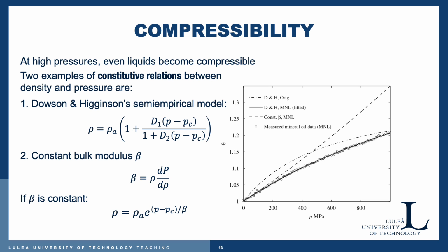So you can see that it's very well suited to represent the pressure-density relationship for this mineral lubricant in a whole range between 0 and 1 gigapascal pressure actually.